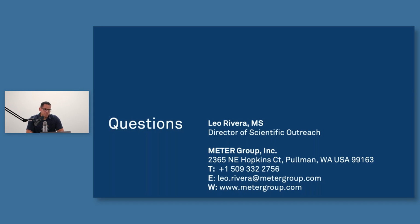And so to touch on the installation orientation question first, I do think the orientation impacts the measurement, especially with the 21. Sometimes we see people install the tensiometer or the TEROS 21 with the plates horizontal. What happens there is that actually creates a little bit of a shadow to the water, because it blocks the water as it's moving down. And so you can have one plate that's reading wetter and one plate that's reading drier. So I always recommend installing the TEROS 21s with the plates oriented vertically to limit its impact on water movement.